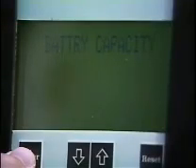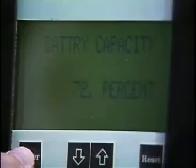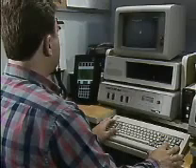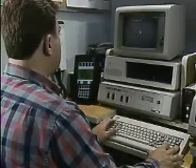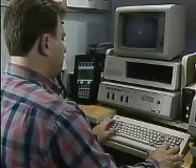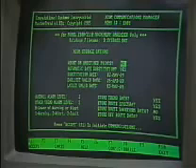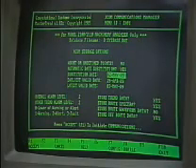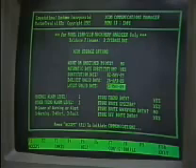Before a computer-based vibration analyzer is used, the batteries that power the data collector should be checked. Information about the machines that are to be monitored is transferred to the data collector from the computer. This information may include the types of machines being monitored, the locations of the machines, and the specific points on the machines where the transducer will be attached.